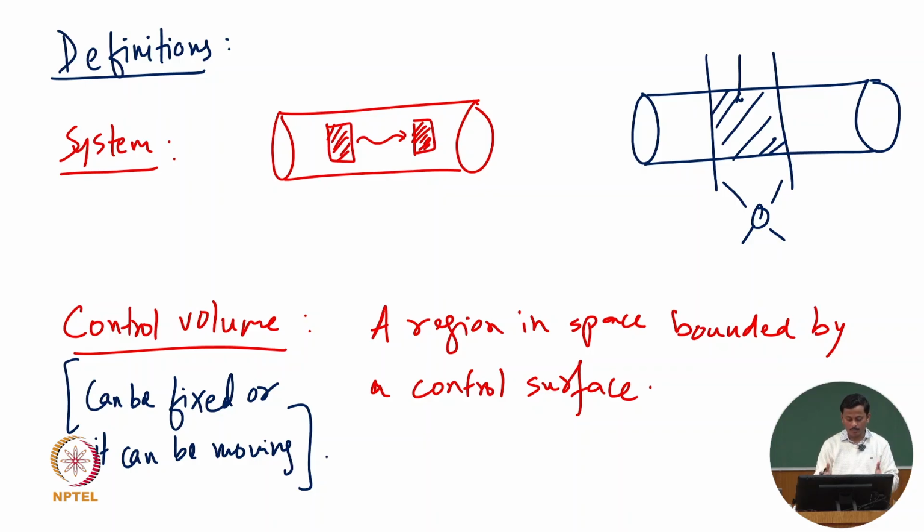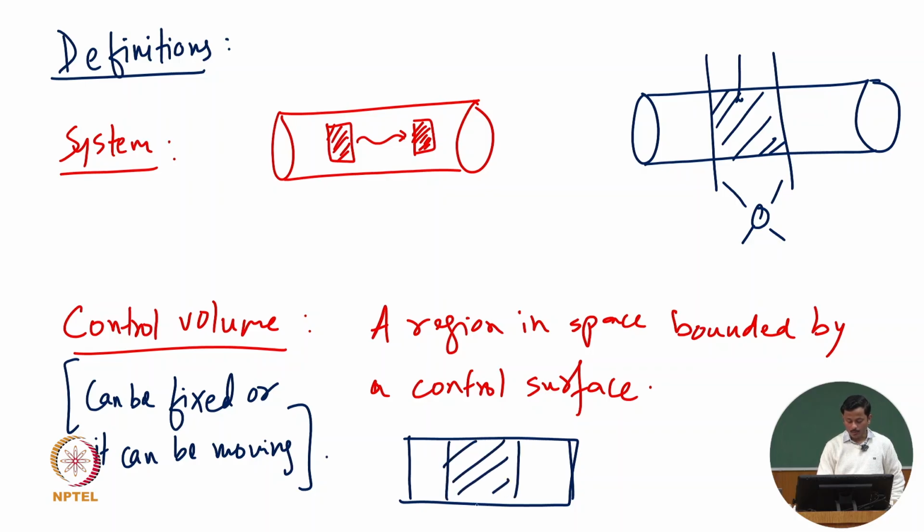Which means we are essentially employing an Eulerian approach here. So we have fixed a region in space that we'll always study. For example, as I've given you, this is a channel flow, this is a pipe flow, this is a region of study, and we have fixed it. This whole thing can be moving. It can be on a trolley, it's moving, but you have fixed your region of interest and you are doing some measurements in this region, and this is called the control volume.